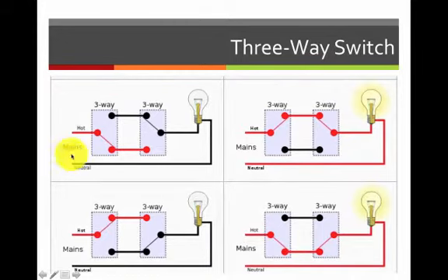So for instance, if on this first switch you were to flip it up, like you walk in a room and flip the light switch on, it would give you the scenario here on the right. It went up, it made contact with the upper traveler, which was connected on the other switch, which we haven't touched, and thus completed the circuit in red. And the light bulb is lit. Notice that the bottom traveler doesn't have any connections, it's just there.